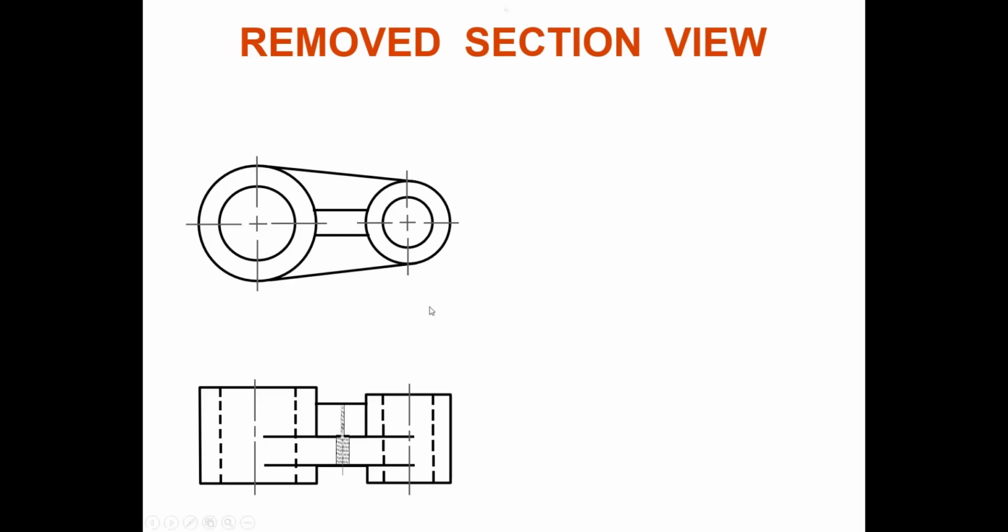Okay, revolve section. When you cut, your cutting is at the center line. Actually, it's an inverted T section shape when you cut it. By this section, people read, oh, this cross section is an inverted T section. They understand it. That is the idea of sectioning, to facilitate drawing, to facilitate dimensioning, to facilitate viewers to read your drawing.